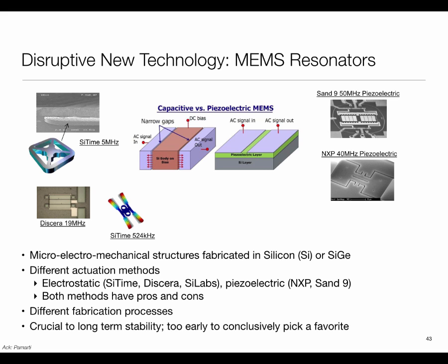There are electrostatic approaches, there are piezoelectric approaches. The main beauty of these is that your clock is sitting right next to your circuitry. So you don't have any additional package outside. You don't have to feed the clock from outside. It saves on board area. Even though the resonators may not be that good, you can now throw processing at it, more signal processing, more control, to get more stability out of them. So there is a lot of interesting stuff happening around this.